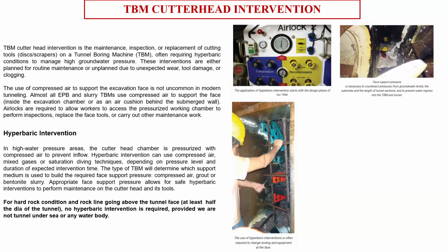And then when we have a very high overburden, or open ground where we don't have any structure, and the ground is also competent, we have applied a face pressure of 1.5 bar, 2 bar, and made the TBM progress faster. So both depend on your groundwater scenario and also your operational issues. So TBM is basically not purely design. Some matters are also decided with respect to the operational part.